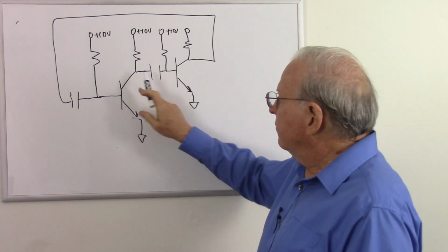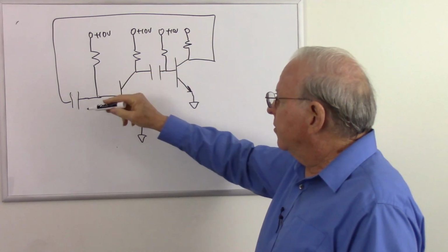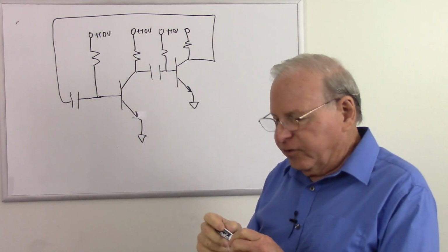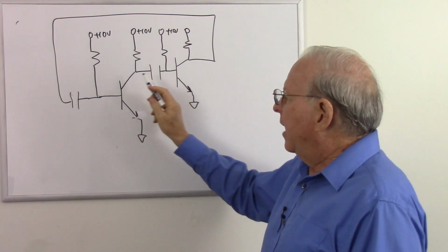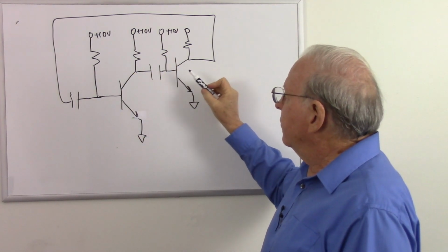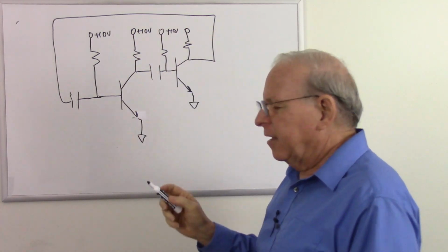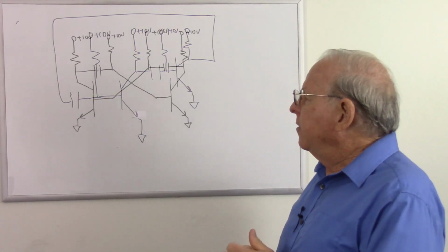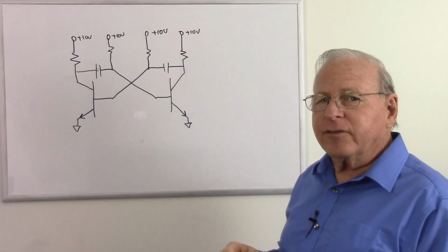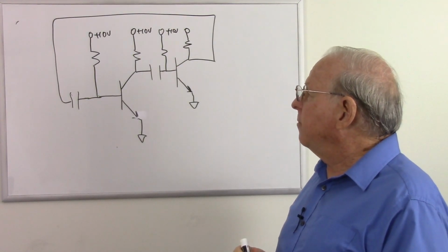These capacitors give us our time delay that we need to get this to actually oscillate, and we do have that 180-degree phase shift. So these capacitors will add the time delay that will cause this to oscillate, and we also have the positive feedback, so this will oscillate. Now the astable multivibrator is usually drawn a little differently, like this, but this is exactly the same circuit.